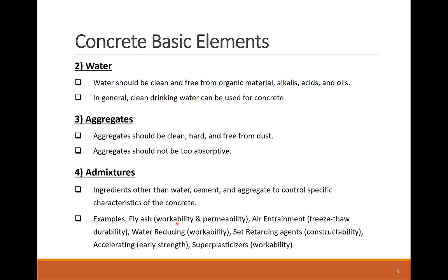Water-reducing admixtures are groups of products that are added to concrete to achieve certain workability and slump value at lower water to cement ratios. Additive retarders to the concrete mix delay the hydration of cement without affecting the long-term mechanical properties. They improve the concrete constructability in situations where mixing and placing occurs at distant times, like in long distance hauling between the batch plants and the site.